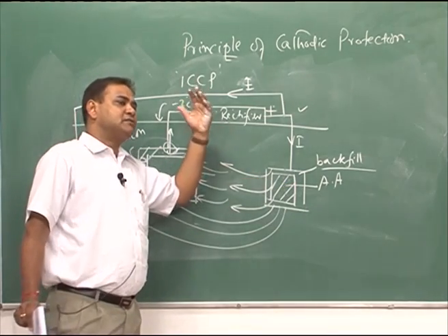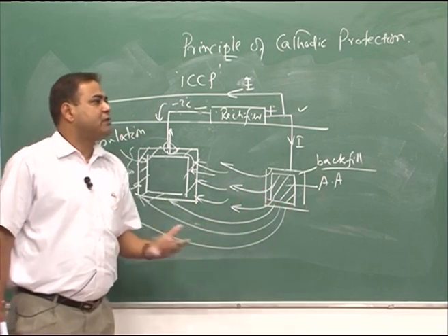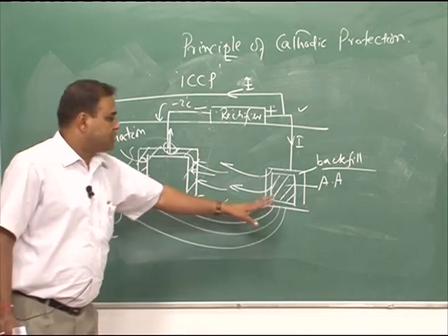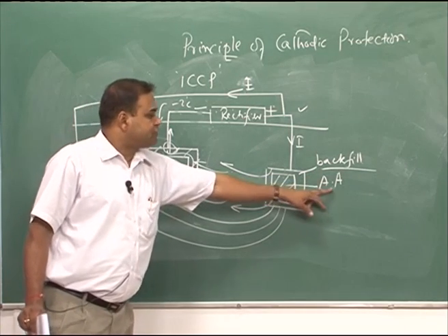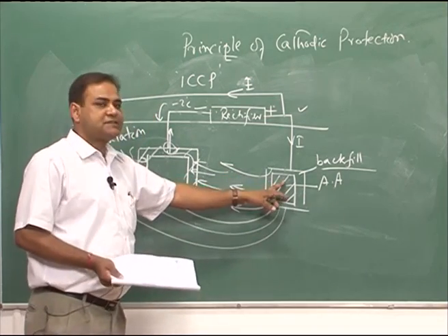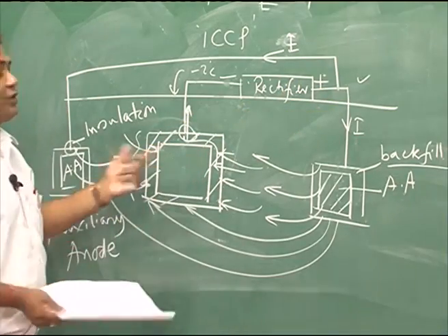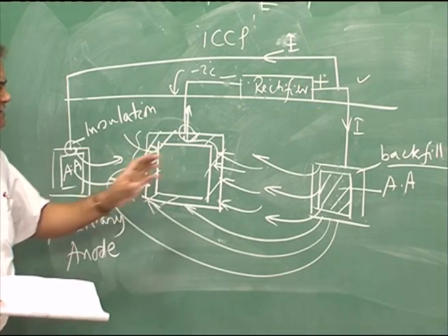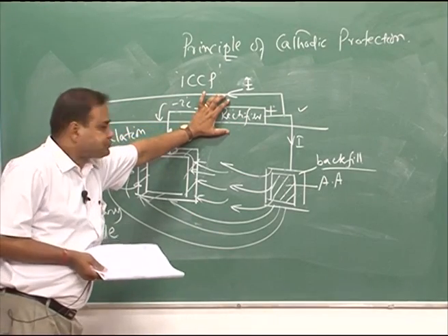In the sacrificial anode case, we need to see what the ampere hour is for that particular anode material, but here we should not bother about that, because once we fix an anode material which is not self corroding in the system, and if we can keep on sending this current, we can have protection.